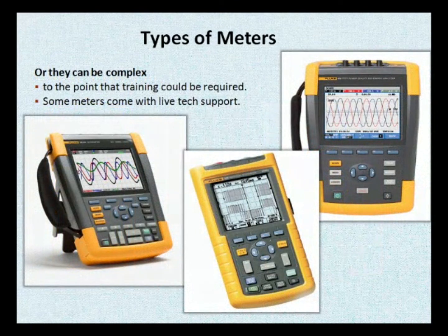For example, you could use a multimeter intended for cat 4 to measure cat 2. Yes, you can. But not the other way. Just want to confirm that. Yes. Because if something is designed to be heavily used, you can measure something that's a toy, right? But if you have something that can only handle lower voltage, and you start measuring higher voltage, you can get yourself into trouble.